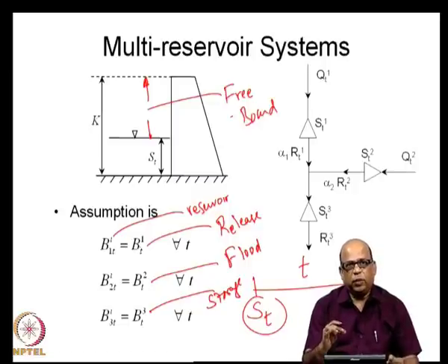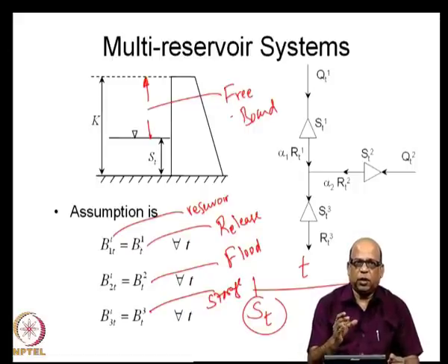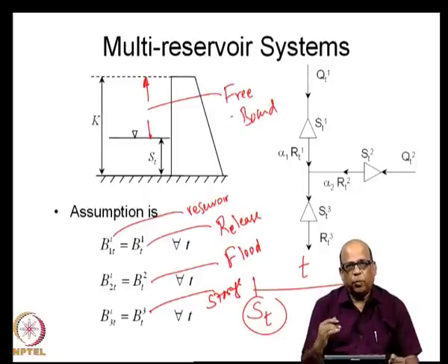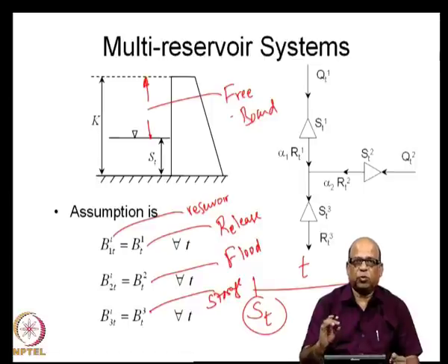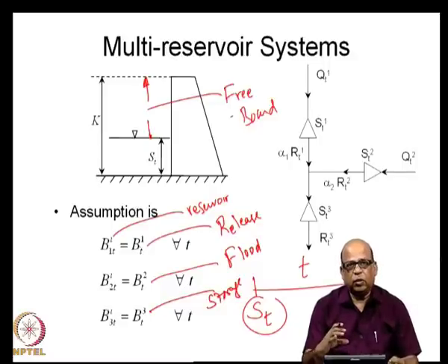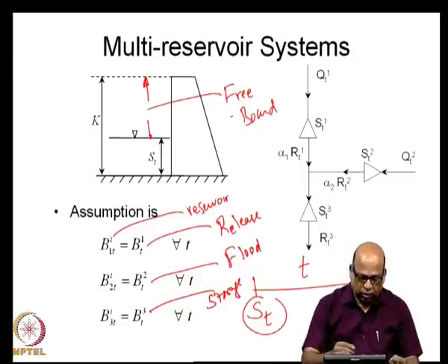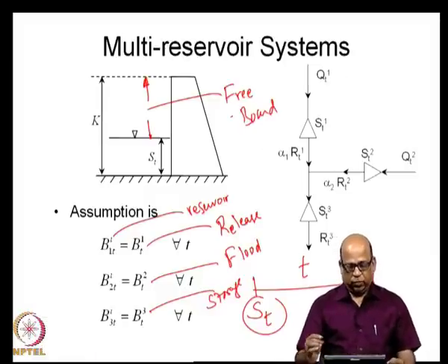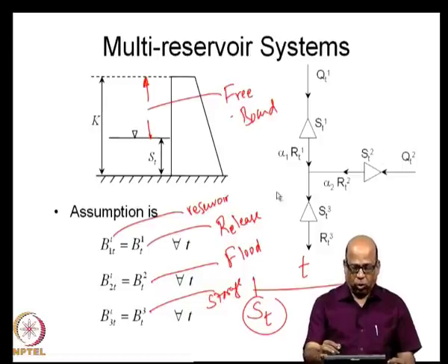If you are specifically interested only in irrigation and hydropower, you may still reduce the time period to 10 days, and if you want to operate it mainly for flood control, your time periods can be even smaller, let us say 1 day time period, 6 hours time periods and so on. Now, these kind of sophistications we can include when we are going for real time operation. So, let us look at how we determine the reservoir operating policy for this kind of system, looking at all the reservoirs together.